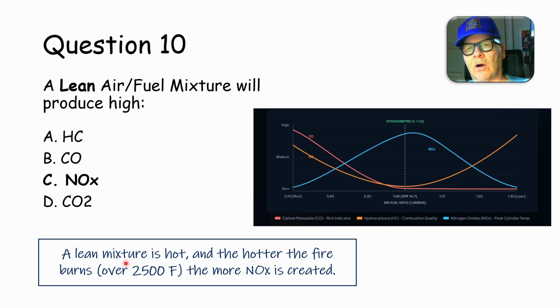But the EGR, when you put inert gas in there, it doesn't burn, because that inert gas basically makes the combustion chamber run just cool enough during the combustion event that it doesn't make as much NOx. And so, of course, they're doing EGR on diesels now for that same reason.